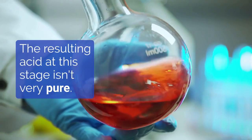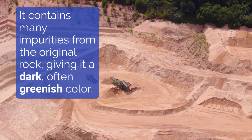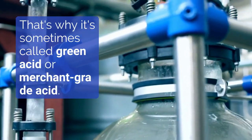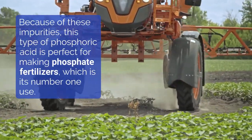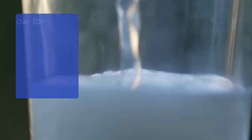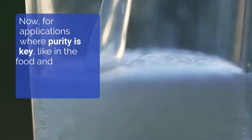The resulting acid at this stage isn't very pure. It contains many impurities from the original rock, giving it a dark, often greenish color. That's why it's sometimes called green acid or merchant-grade acid. Because of these impurities, this type of phosphoric acid is perfect for making phosphate fertilizers, which is its number one use.